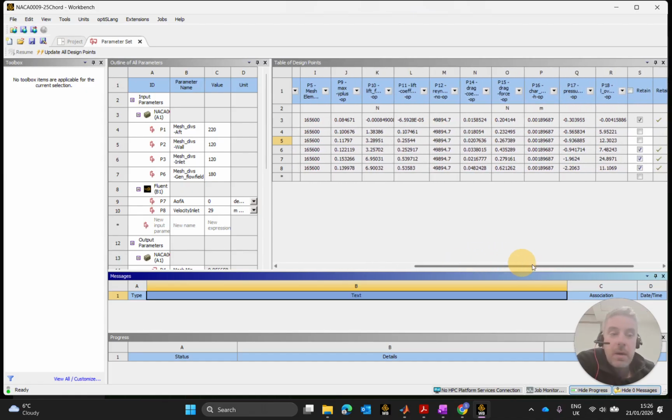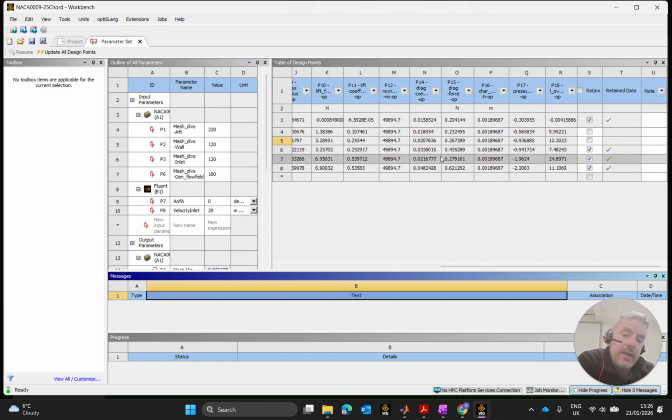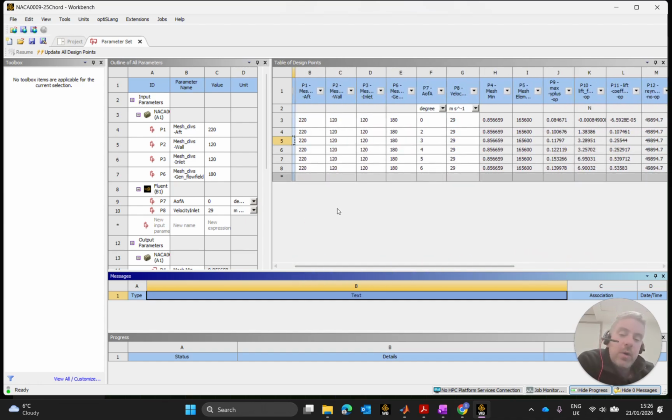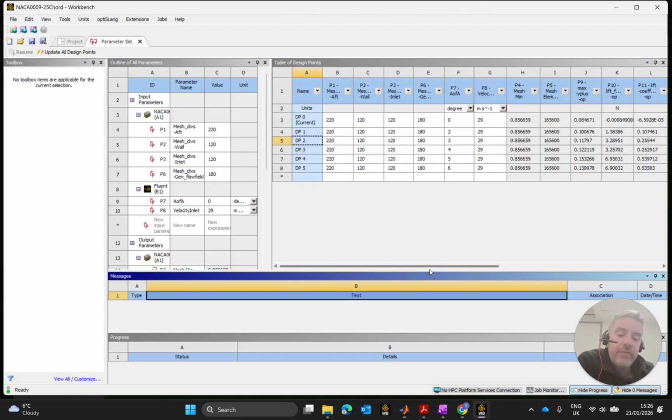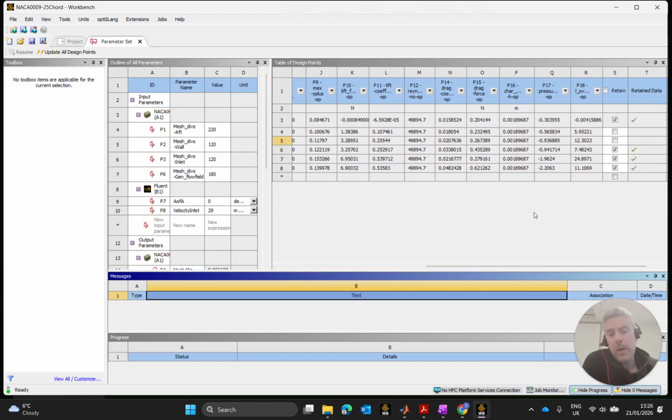We now have more tools to get to the bottom of it, simply by virtue of the fact that I retained the data when I ran the calculations for design points 3, 4, and 5. So what we can do is pop into the solver and see what's happening at these design points. My first place always will be the contours, because we might see some indication of certain drops in pressure at different locations, or reductions in velocities where we normally shouldn't have.